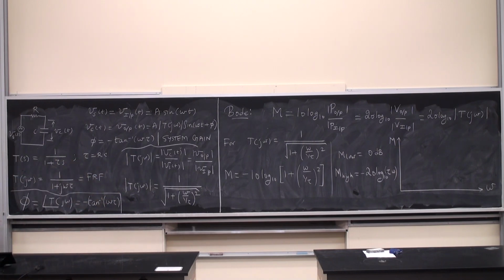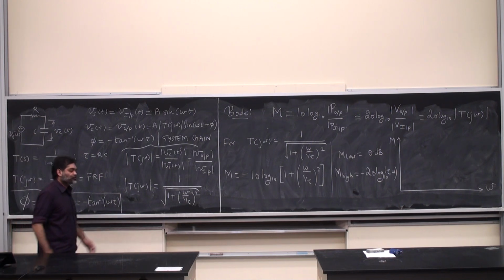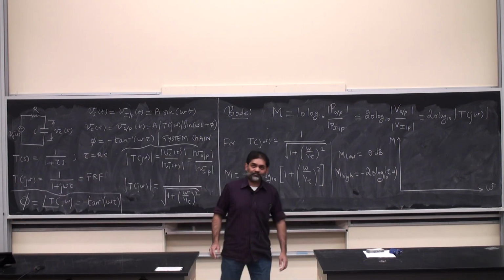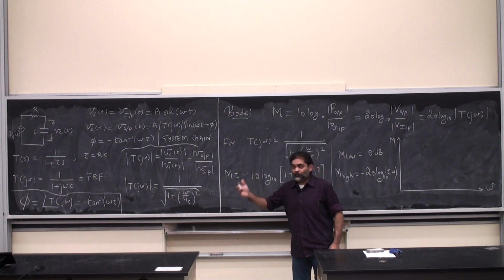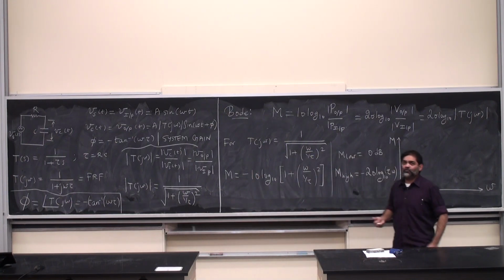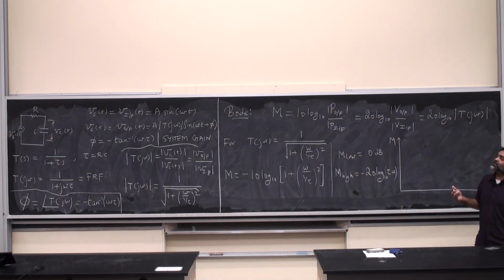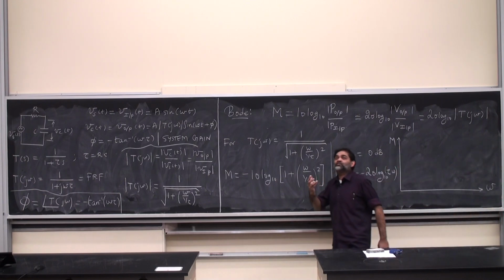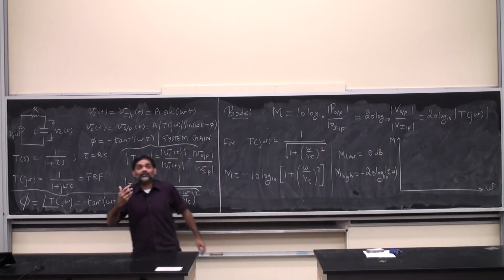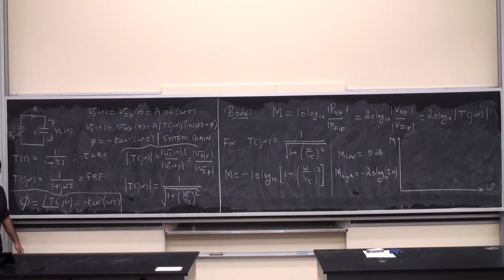So in the homework or in the exam, I'll tell you, here is a circuit, obtain its frequency response function. What do you have to do? You have to use a method of impedances, and we're going to solve some problems, of course. You'll come up with a transfer function of the system relating the output and the input. You convert it into the Fourier domain. Essentially, we are doing a Fourier transform here by converting S is equal to j omega. Once you do that, you get your frequency response function. So this is the key to all of our calculations.